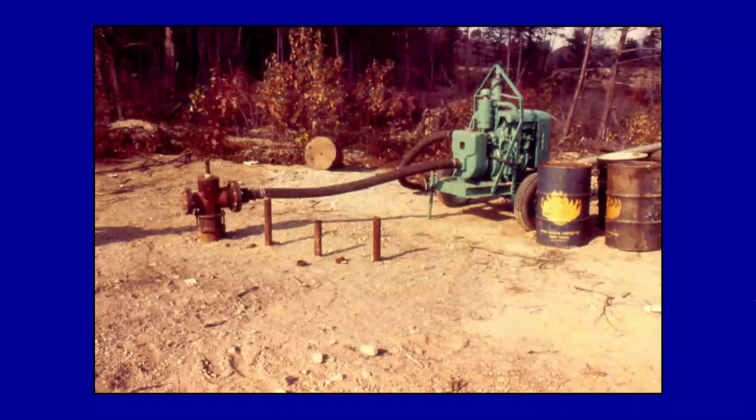Wells can be pumped with a suction lift pump if they are shallow. But remember, a suction lift centrifugal pump can only draw water from a depth as deep as 24 feet beneath the surface. So in a very shallow aquifer, a pumping test can be conducted with a suction lift pump. However, in deeper wells, most are now conducted with a submersible pump powered by a generator.